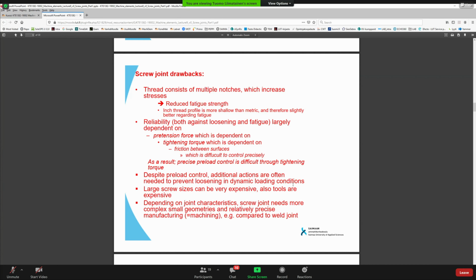There's a slide of it in the later stages. We can look further into it. So basically, you could say that applying a tightening tool, rotational tightening, is never very accurate. It cannot be, because it requires such accurate knowledge about the friction.